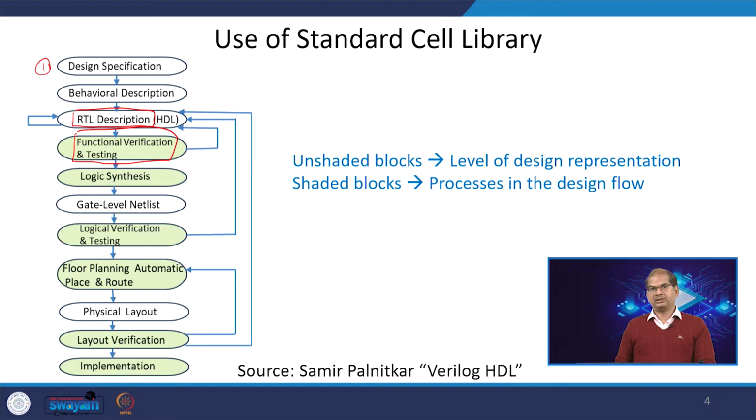Verification is of multiple types; here we are doing functional verification. Functional verification means that the RTL you have written works as specified in the behavioral description. If it is not meeting the requirement, then we will go back and modify the RTL.